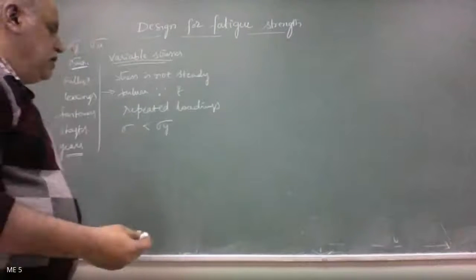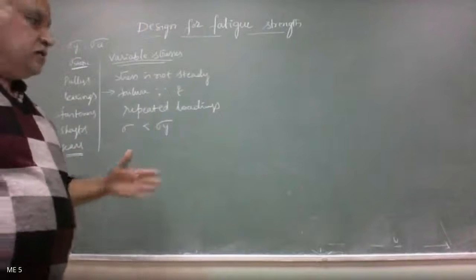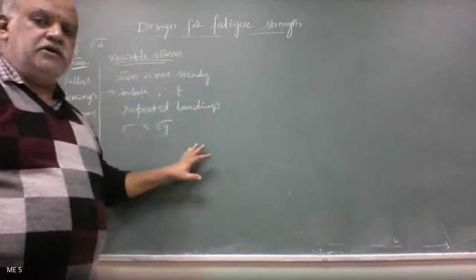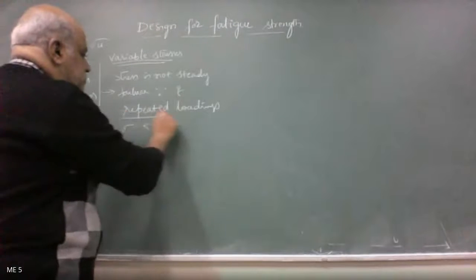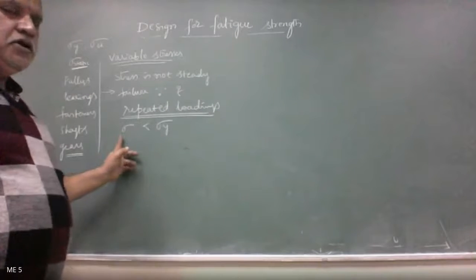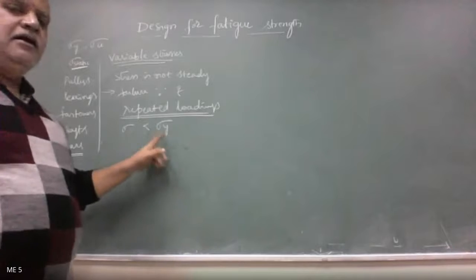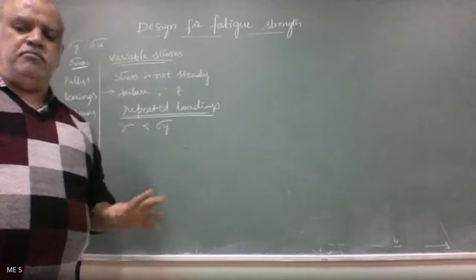They may fail after, say, 5 lakh or 6 lakh cycles. So most machine components fail because of such repeated loadings, even though the stress induced is less than the yield stress of the material.